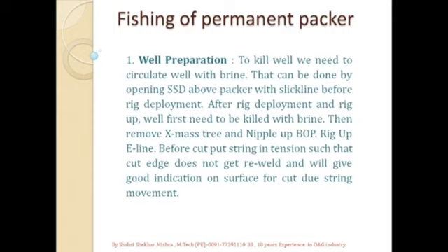After removing the tree, we nipple up the BOP. Once the BOP is installed and pressure tested, we pick up the string, unset the hanger, then pick up the string and keep the tubing in stretch condition, 5 to 10 kips above the string weight.